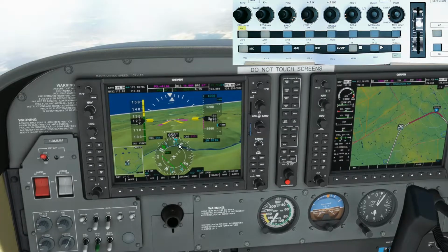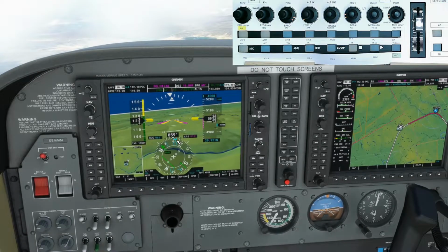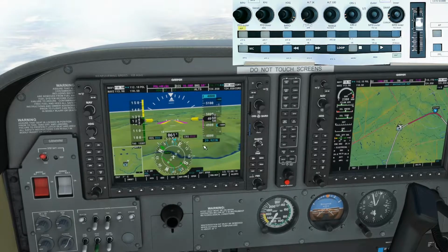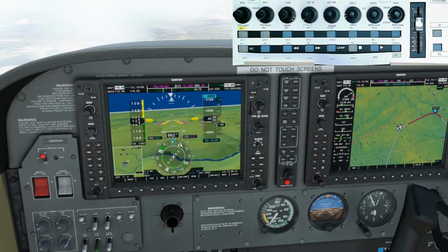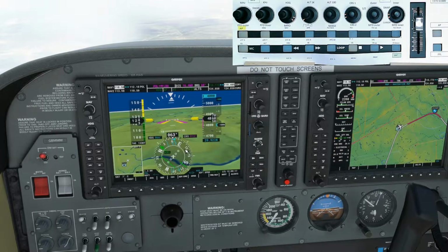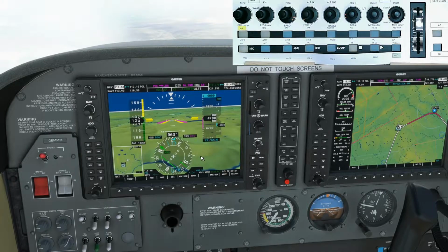So particularly flying on ADF, you're really relying on your heading bug, and you need to keep an eye open for any drift from the wind, because it won't keep you on course particularly. But that's it, and that will fly off towards Leeds Bradford quite happily now.